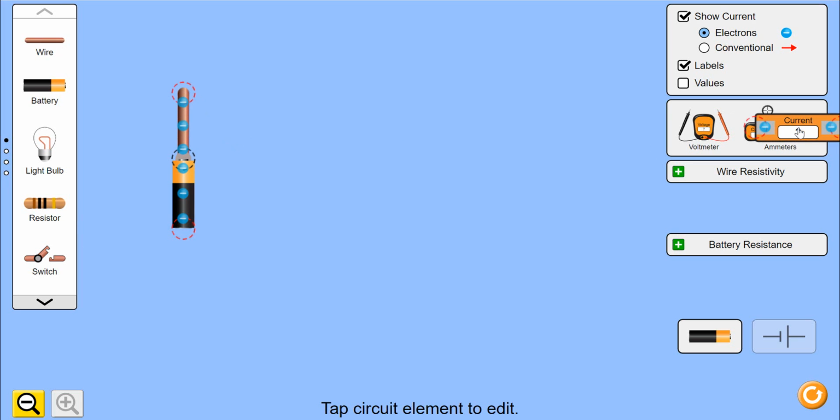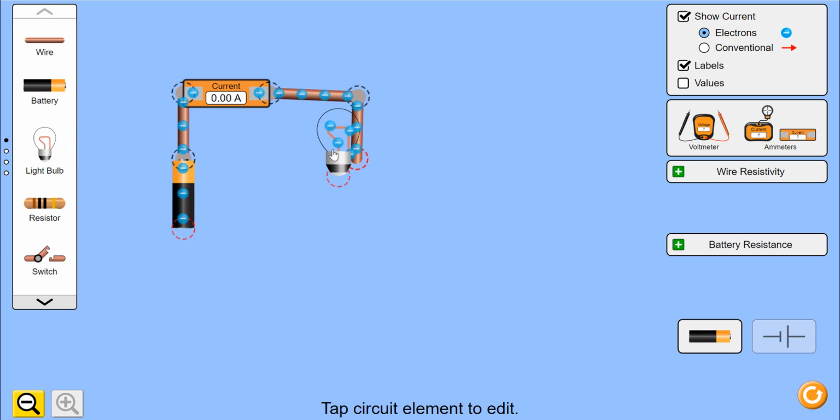In fact, in this case I want to show you something with the ammeter. Ammeters themselves have really low resistance, but they have to be connected in series. Let's just connect them here. I'm going to build down the first pathway. I could really just use a resistor. It would do the same sort of conversion, electrical energy into heat, basically the load will use up the energy. It's much more interesting when I actually stick on a light bulb. I'm going to connect that there, see if I can twist it down.